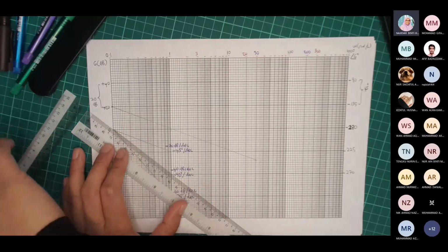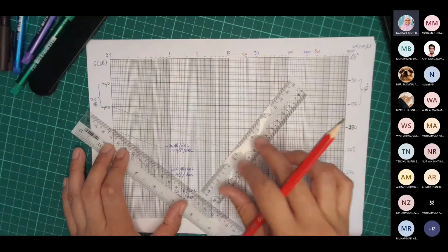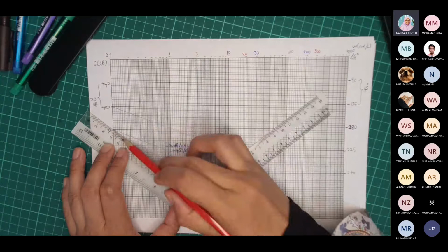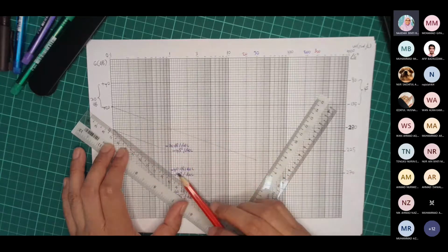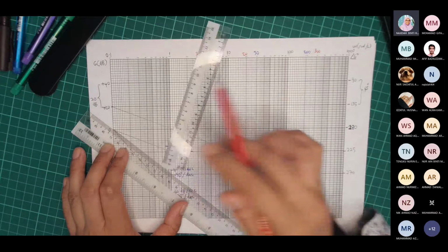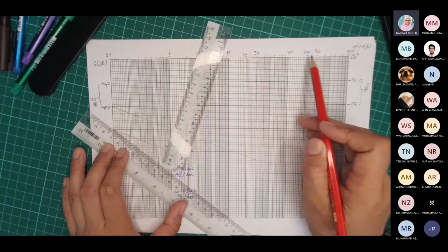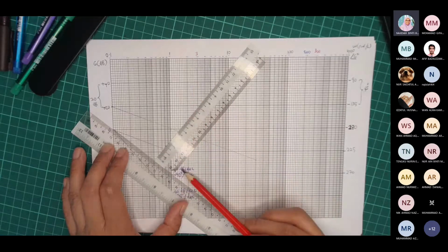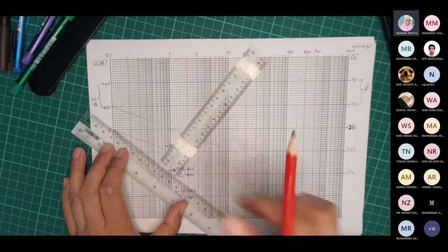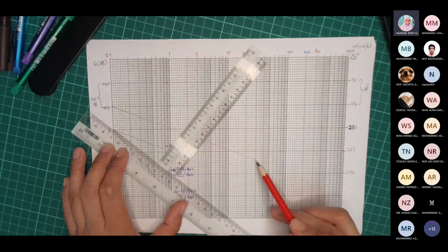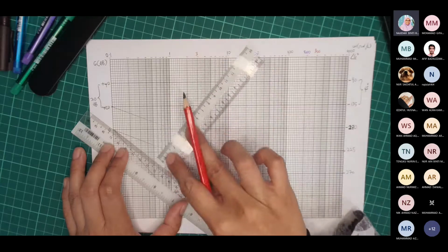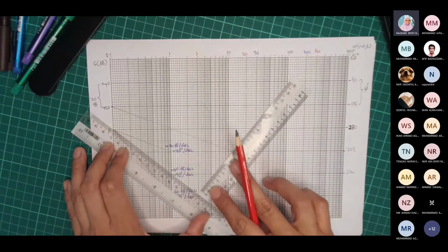Now, take your second ruler. Make sure it is perpendicular to the first ruler. This is our first ruler, referring to the negative 40 dB per decade. We want to sketch from 30 radian per second to 200 radian per second. So the second ruler must be perpendicular to the first ruler, 90 degrees. Then you move your second ruler to the point where you want to continue your magnitude plot, this point at 30 radian per second. Make sure it is perpendicular to the first ruler.